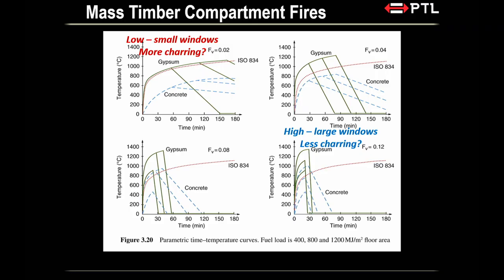That particular test. So you can see, if you just compare the time temperature, these are all time temperature curves. If you just compare the ISO curve to all these other theoretical, realistic fires, you will see that this curve is only one of the many potential fire curves that are out there. So really, this is only for testing. It is not really a real fire. It's just one of many, right?